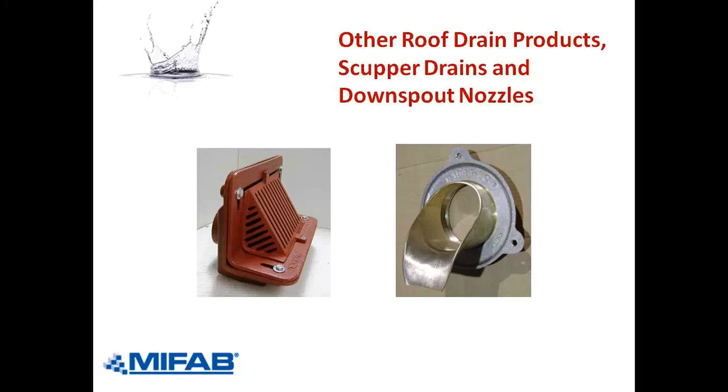So that would prompt the maintenance people to get up there and clean the debris around the primary, because we only want water coming out of this downspout nozzle in an emergency. We have a huge rain overwhelming the primary. That shouldn't be the case either, because the primary should be sized to handle a 100-year rainfall. The more likely case is the primary drain is blocked.